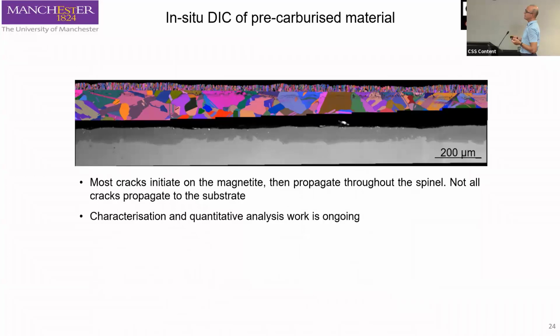Here we have an SEM montage. The field of view is about 1.5 millimeters, and at the top we have an EBSD map of the entire region, and in here we can see the cross-section. We can see an inner and an outer oxide with an irregular interface. Interestingly, we can detect the difference between the inner and the outer oxide, because the outer oxide is ultra fine, whilst the inner oxide grows in an epitaxial way with respect to the substrate.